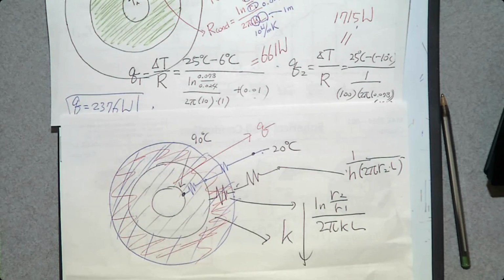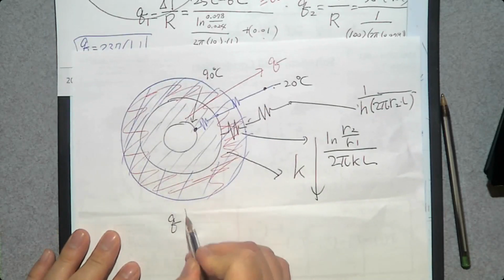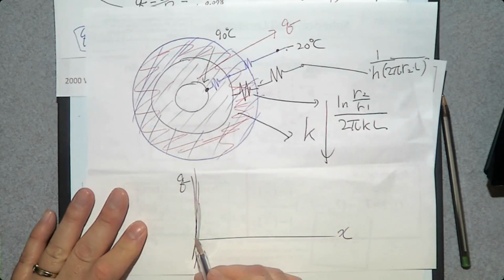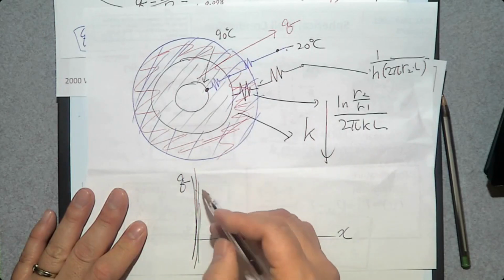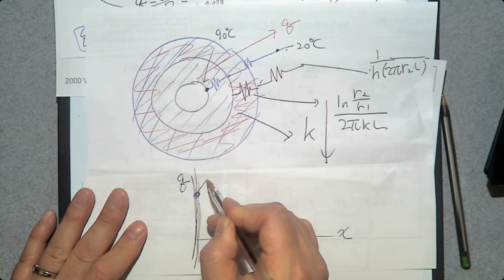So what happens is that if you add the insulation, let's say that this is the heat transfer. This is the thickness of the insulation. If you add the insulation, we expect heat transfer goes down, but not necessarily. Heat transfer actually goes up. The thickness of the insulation is not thick enough to provide enough conduction resistance, but you are decreasing convection resistance.